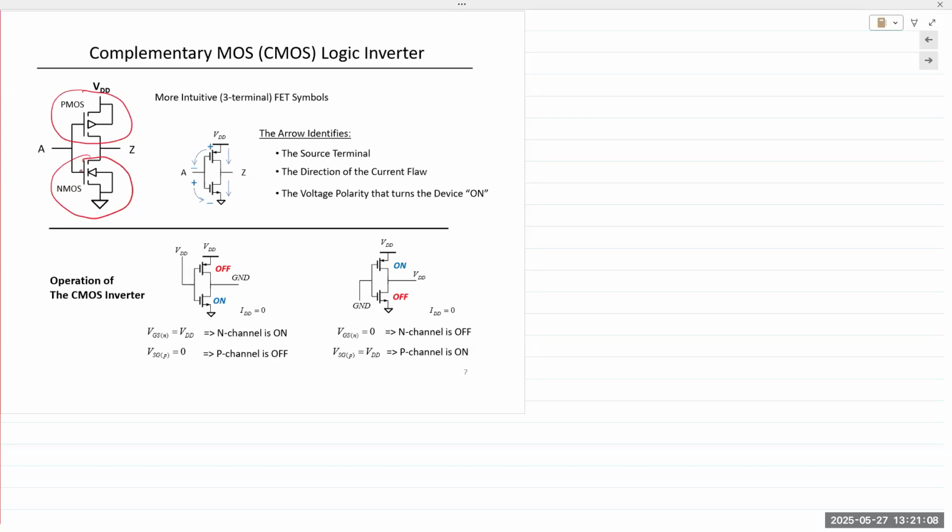If you apply voltage to it, current is going to flow through. Electrical energy is transmitted to the resistor and dissipated as heat. So there's power loss. There is no true on or off. But if you replace it with a BJT or a MOSFET, then you have the ability to actually turn the device off. And when the device is off, the energy consumption is very, very low.